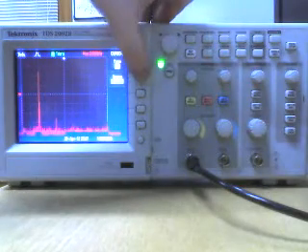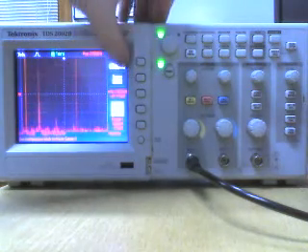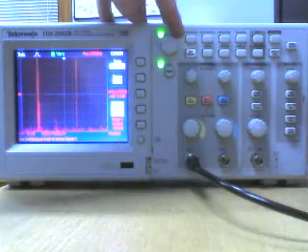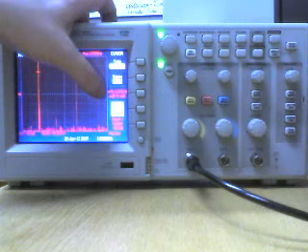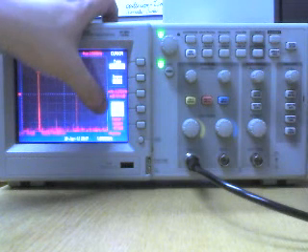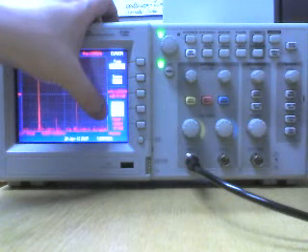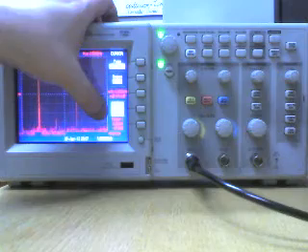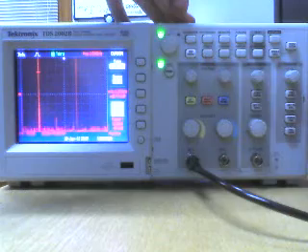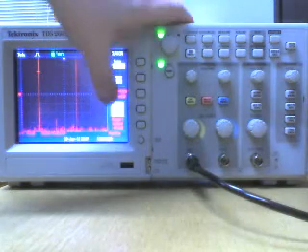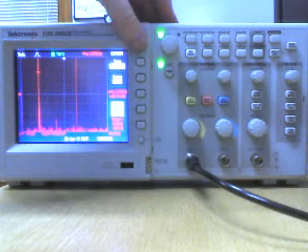You can use cursors. For the source, you want to change it to math because we're in math, and you can change the type of measurement to magnitude or frequency. For frequency, you can move the cursor to our peak, and cursor 1 is at 1 kilohertz, and our magnitude is minus 3.39 dBs. Simple, done. Obviously, this is in dBs, which is a complete pain, so you'll have to convert to volts.